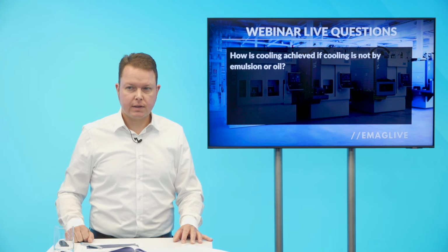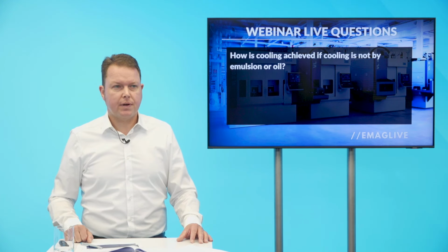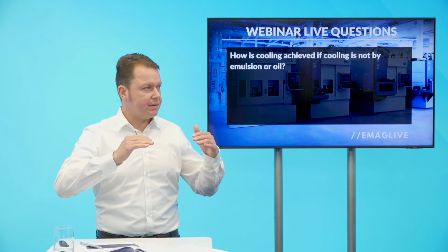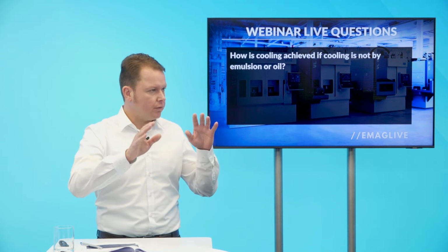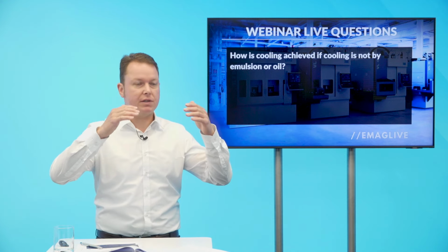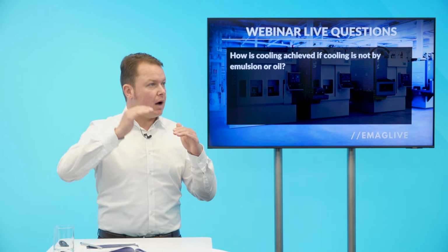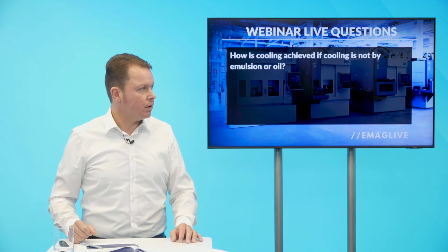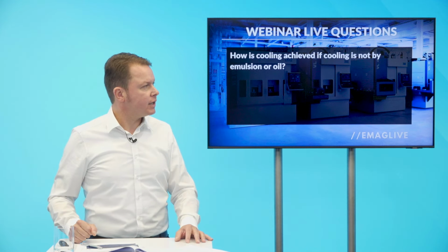Okay, but then some slides before we learned that the coolant pump needs 1200 watts of the energy or of the power of a machine, and all of us knowing that compressed air is a really expensive good. Yeah, of course. Compressed air, indeed, you are right, Heiko, is very expensive, that's clear. But we will see that the benefits of dry hobbing, when we have, of course, always under the condition that we have the required quantity of parts to machine, the benefits are way higher in comparison to what we spend on the compressed air. But I'm going to show you this a little bit later on.